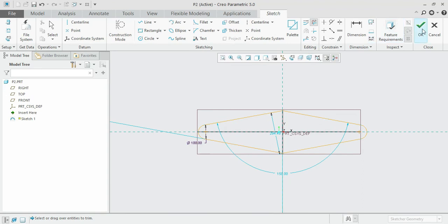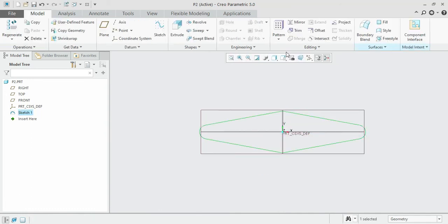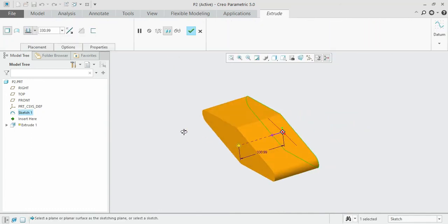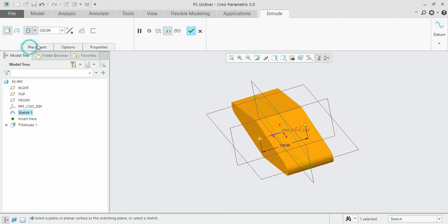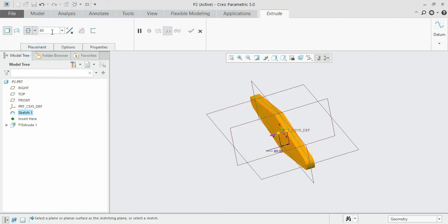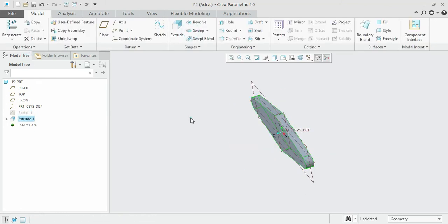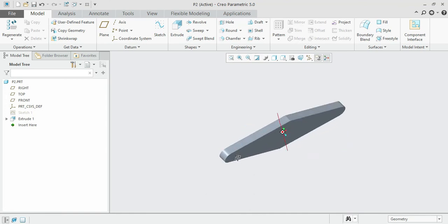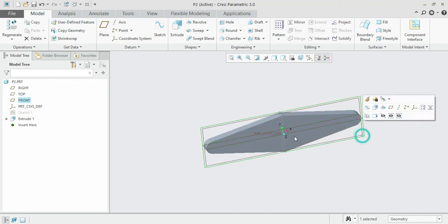We shall first extrude it. Press the mouse button to find whether it is a closed one. Yes, it is the closed one. Let's click OK and extrude it. Extrude equally between two layers and enter the dimension as 60, plus OK. We are finished. Now we shall extrude the three circular tubes. Okay, one over here, one over the middle, and one over the corner.